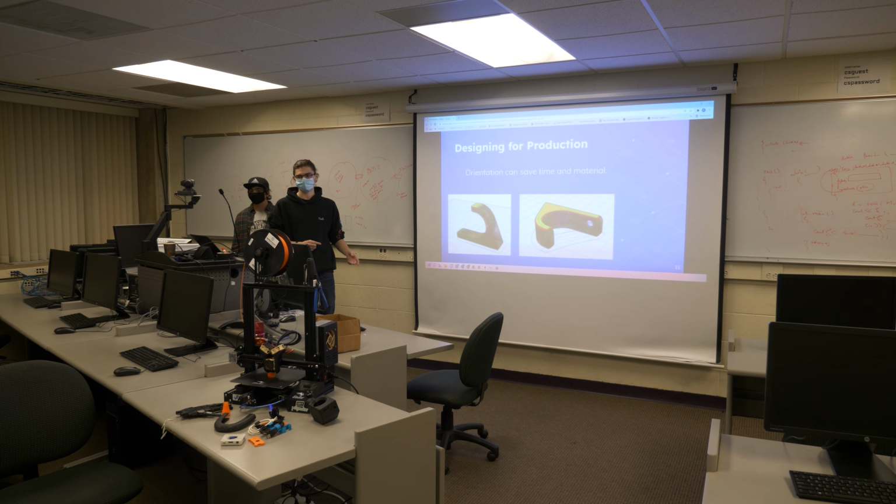So keep that in mind when you're printing things, and keep that in mind for how you're designing things. Doing force analysis on 3D printed parts is really difficult and not a perfect science yet, because you not only have these different directions, but you also have infill. The part is not completely solid, and you have different varieties of infills, different thicknesses of walls, all settings that you can play with. And so doing force analysis on them is a little bit difficult, and you've got to take that into account when you're designing.